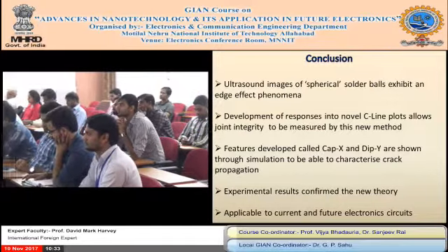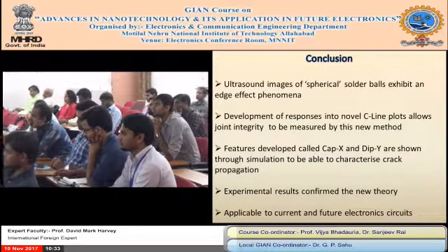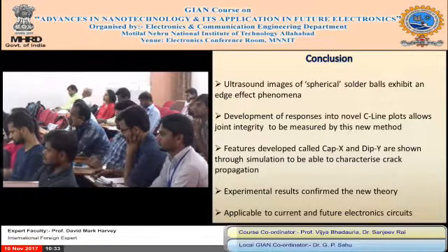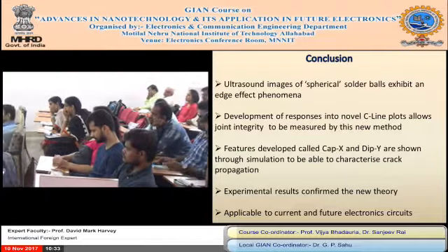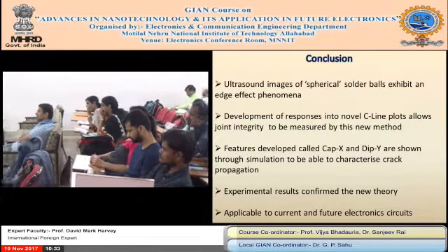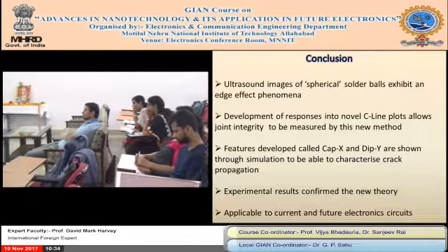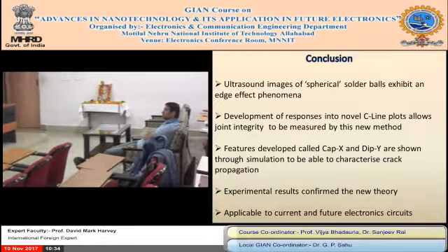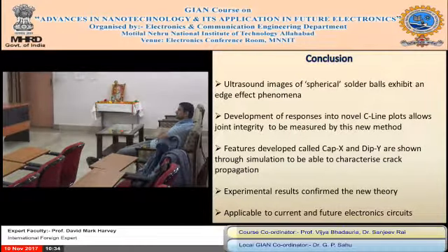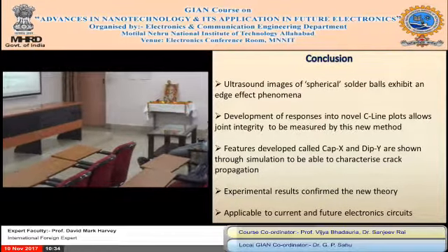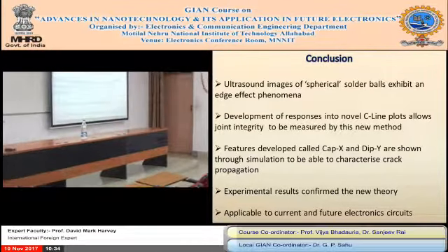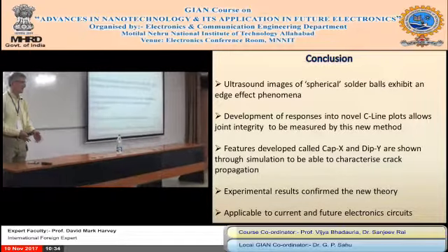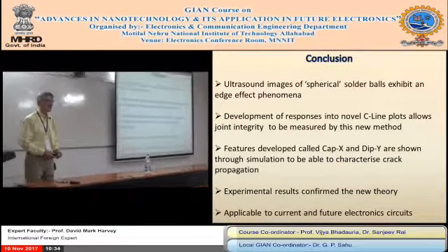So this was applied to this flip chip, 109 solder joints of about 140 micron, but with the right machinery you could apply it to any product. Same technique if you're soldering products. Solder joints now I've seen down to 40 microns or less. And then what about if you get a nano particle, 5 to 10 microns of the solder ball? That could be the future, if you can make it. The trouble is, how do you make these things get smaller? And that's for you to do, not me. I'm too old now.